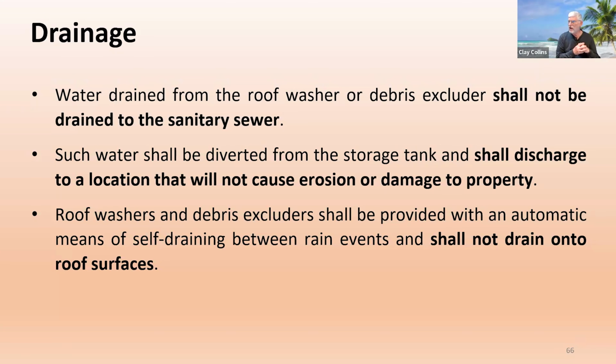Roof drainage onto the AC condenser. If I see that there is no protection over the condenser, I've already recommended gutters and downspouts. If they don't choose to do that, quite often you'll see that angled aluminum, call it a splash guard, and it runs down there and hits.